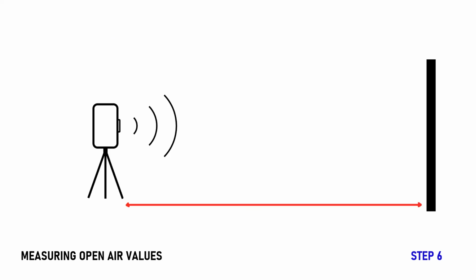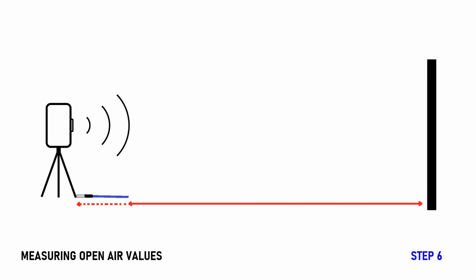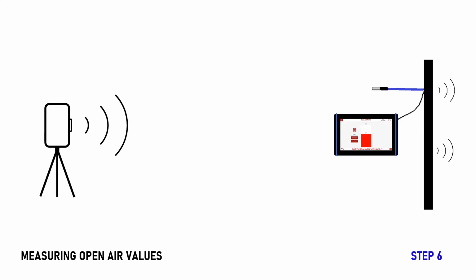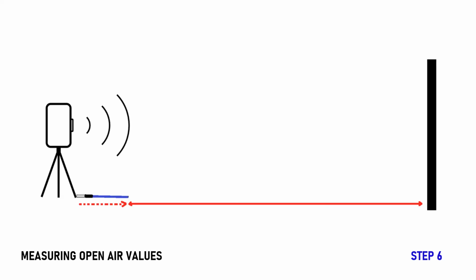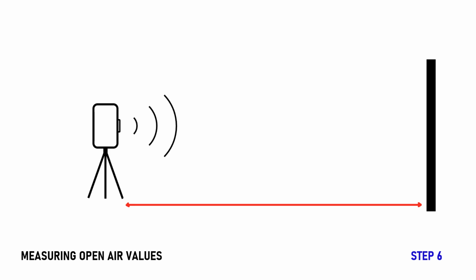For an unopenable structure, move to the same side of the structure as the generator. Position the generator one wand length further back from the structure. And position the receiver in front of each leak as shown. Take the measurement by pressing the Measure OAV button and repeat for each leak. Don't forget to move the generator forward again once all OAVs have been measured.